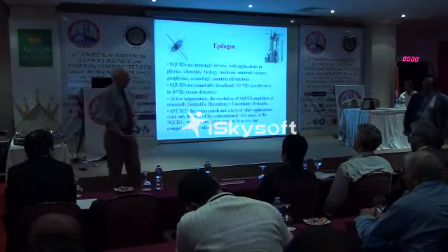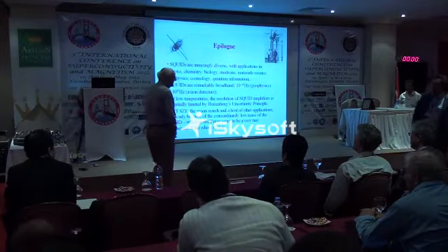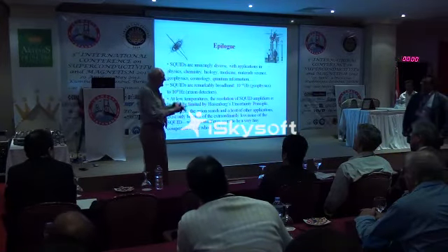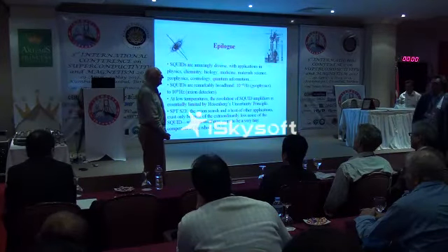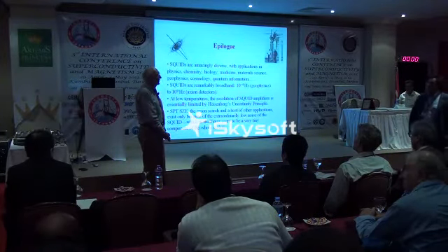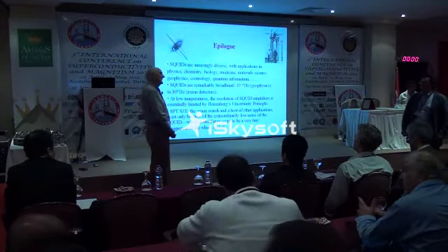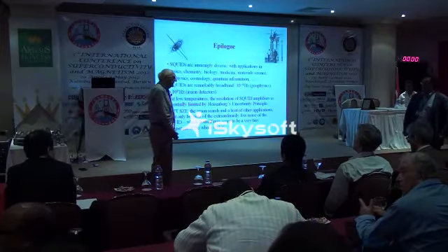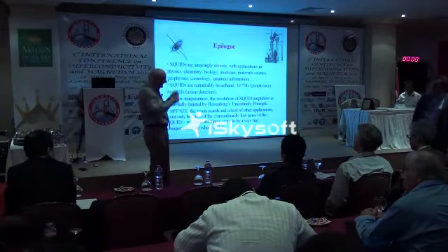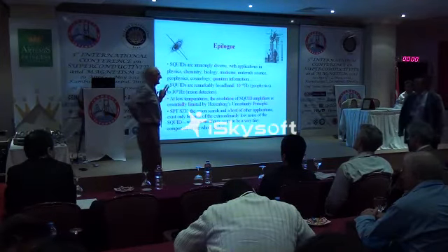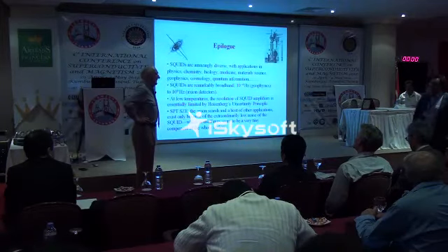The other thing that remains to be solved is the problem of flux noise in SQUIDs, which apparently arises when you have multilayers. If that were solved, it would open up more applications of SQUIDs, for example in medical applications, certainly for magnetocardiology and maybe for magnetoencephalography, because you get the high-Tc SQUID closer to the skull. So those are two things that really need to be done with high-Tc.